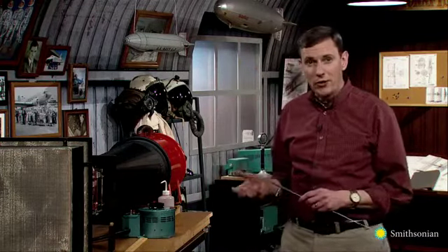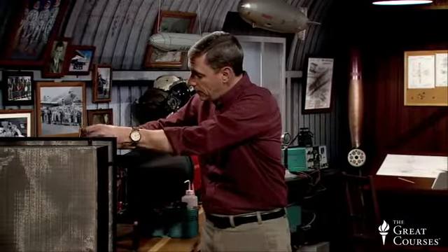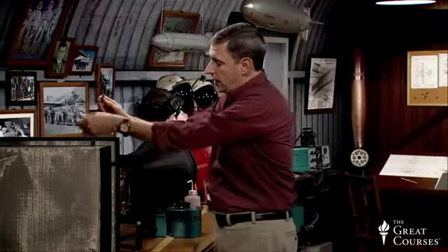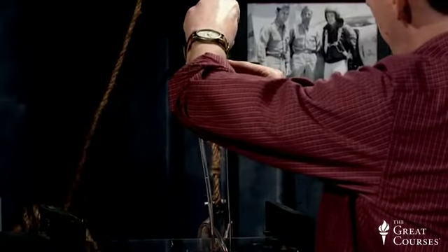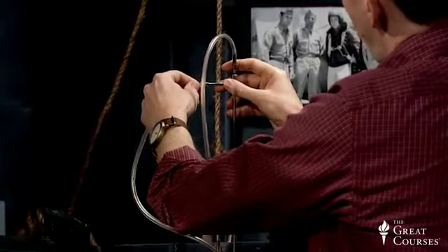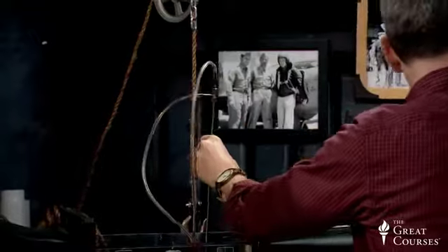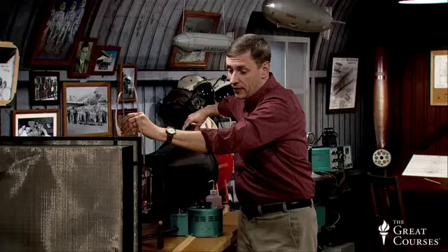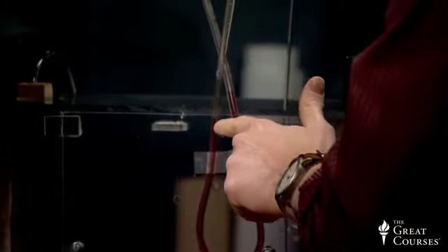All right, I'm now going to fire up the wind tunnel and record the test section speed using this pitot probe. First, I'll put the pitot probe into the tunnel, and I'll connect the left tube to the top, which is the measurement of total pressure. And then the right tube I'm connecting to the port coming out the side, which is the static pressure. Now when I hold the pitot probe in the tunnel and turn the tunnel on, we're going to see a change in height of the water level here.